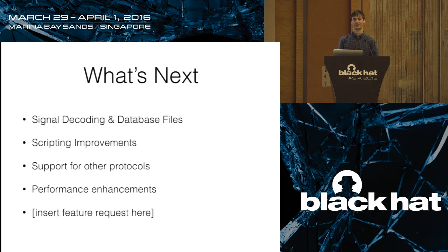No one really uses that except for that CANtact tool. The traditional one is the DBC file from Vector. To be able to take in these formats or edit these formats and then do a live decode of everything on the bus is a next logical step, especially as we're working to make it easier to provide some of that information once you've done the research.